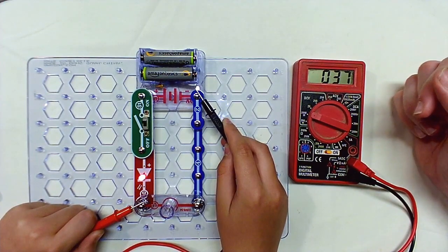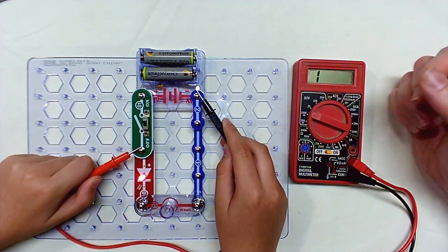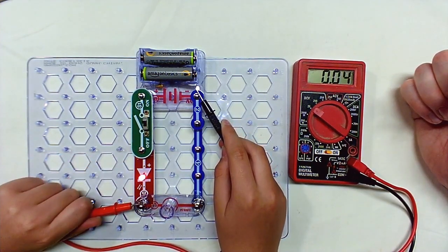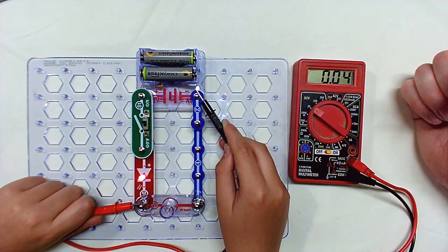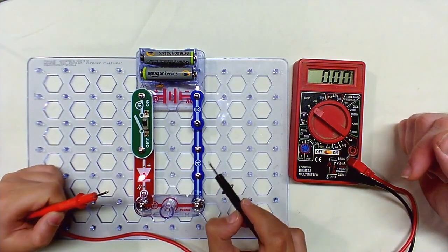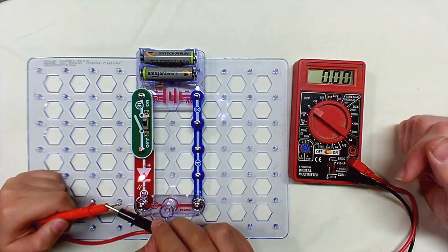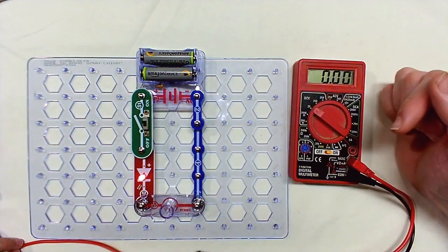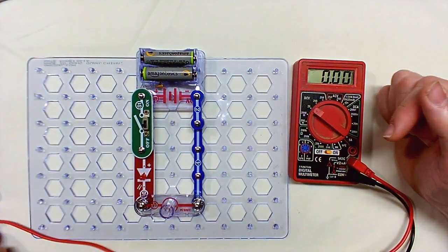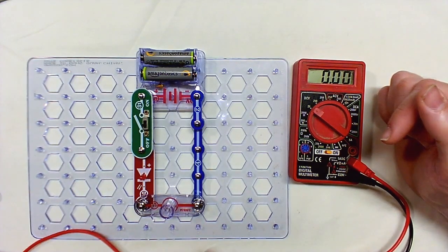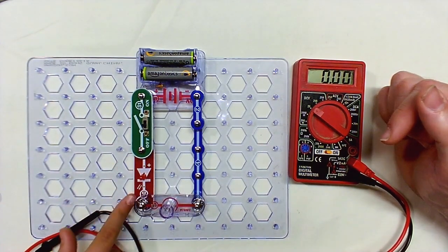So the voltage is dropping quite a bit as it goes through there. Let's actually switch it to here. So 2.5, and then this is a lot less, huh? 0.04, which is way lower. So there's actually a pretty large voltage drop on an LED, especially for the batteries that we have here. It would be easier to see if it was like 9 volts. Part of the reason for the drop, not all of it, but like I said before, there is probably a resistor in here.